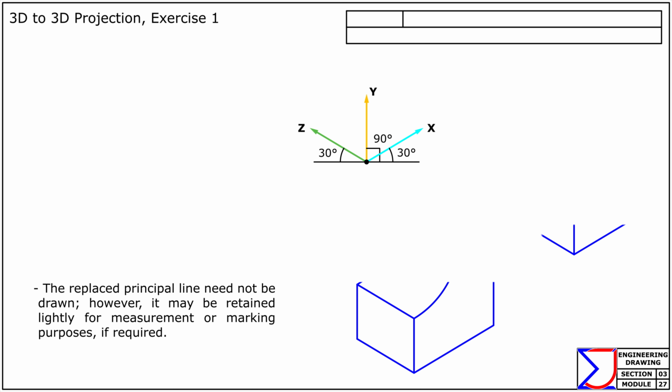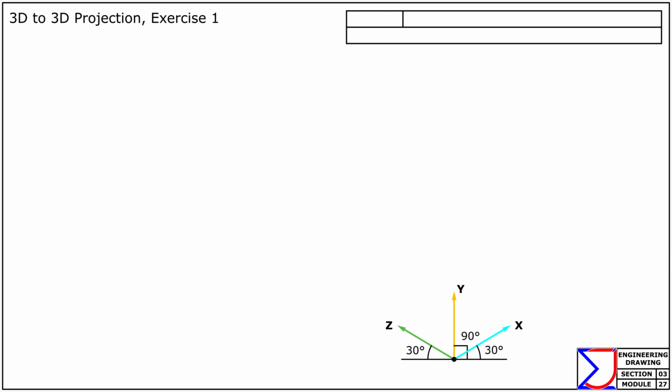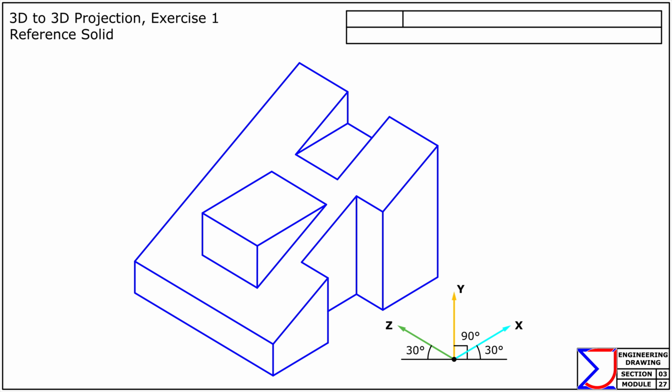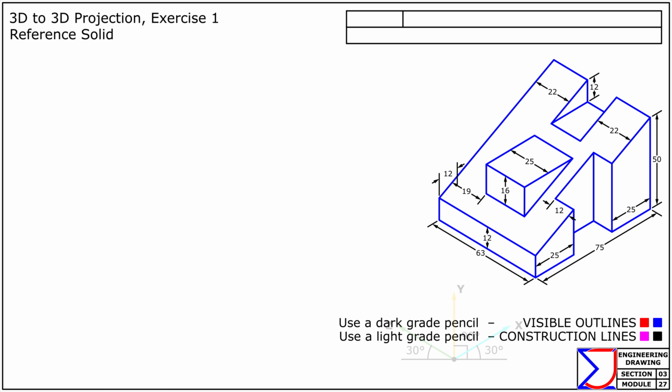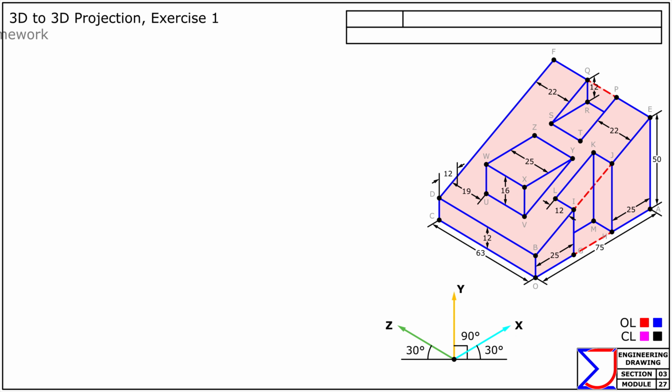Copy isometric view, exercise 1. This is the 3D object we will replicate in our drawing. Observe its structure, features, and dimensions carefully. To begin, we will first identify all the vertices and then randomly annotate them, which will guide us through the step-by-step construction process in the isometric plane.